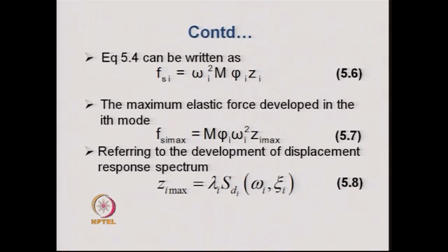Now, let us go back to the development of the displacement response spectrum. If you recall, the displacement response spectrum for an earthquake is obtained by analyzing the single degree of freedom system with a specified damping and a frequency for a given record of earthquake and finding out the maximum displacement.